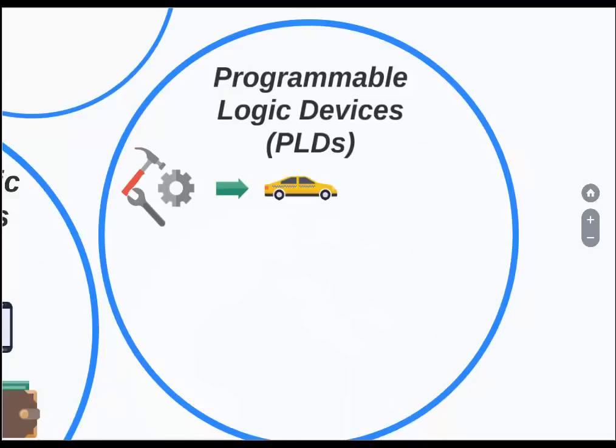With PLDs, designers use inexpensive software tools to quickly develop, simulate and test their designs. Then a design can be quickly programmed into a device and immediately tested in a live circuit. The PLD that is used for this prototyping is the exact same PLD that will be used in the final production of a piece of equipment. Because of this, there are no NRE costs involved, and the final design is complete much faster than that of a custom fixed logic device.